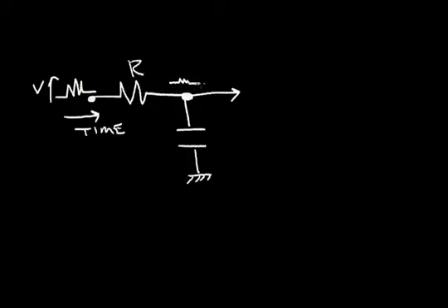It'll be a lot smaller. So the capacitor can be used in conjunction with other components to form a filter. In this case, the capacitor is filtering out noise at the input and reducing it here at the output.